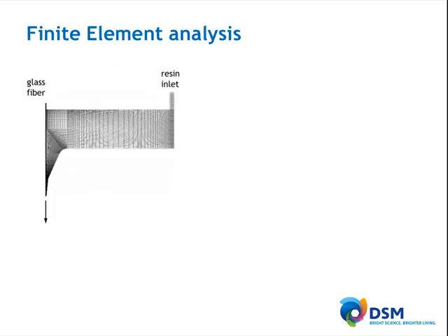Now, if I do the finite element analysis, they showed the grid before, but let's start with a fully functioning system. Here, what I do is we vary the draw speed, slowly ramping up and keeping everything constant. So the temperature is constant, pressures are constant. And typically, from a theoretical point of view, this is really a very nice process because it's a very self-regulating system. You can slowly ramp up without any other external influences, and we can do that in the model. And you can see that the geometry of the primary coating remains almost constant within 1 micron fluctuation.